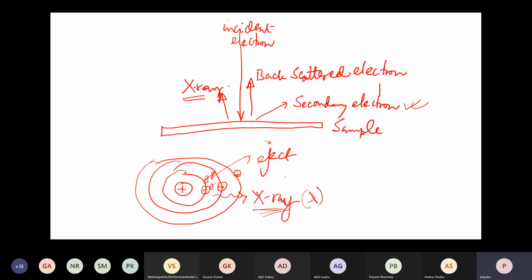So studying X-ray can help you. So SEM does a different purpose. It not only shows you how this nanostructure looks, you can also do elemental analysis. For example, you can use X-ray to find out what elements are present, and in which proportion, in your nanostructure, because your nanostructure might not be made of a single element; it might have different elements, right?